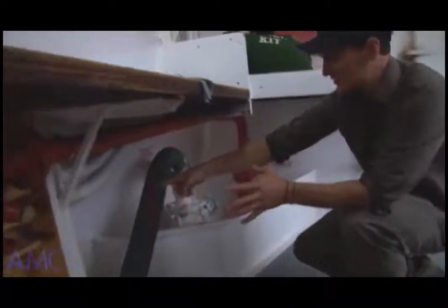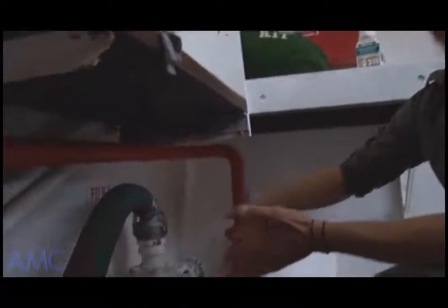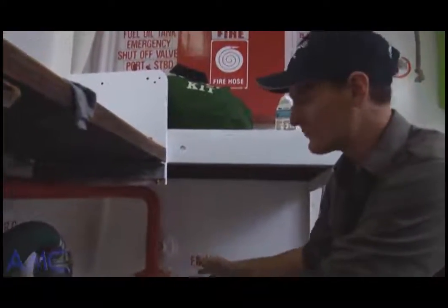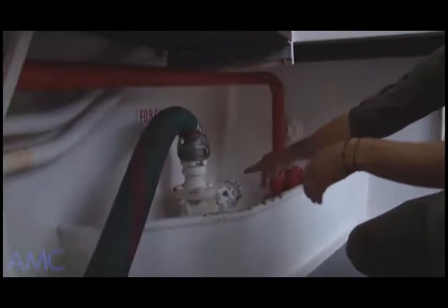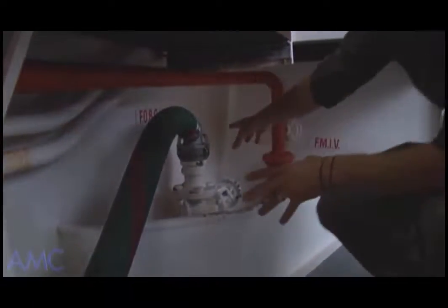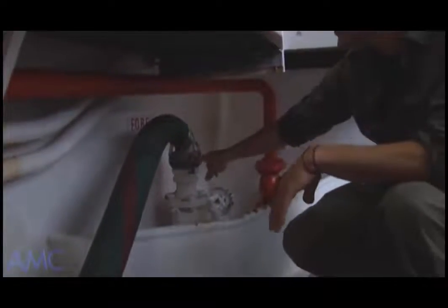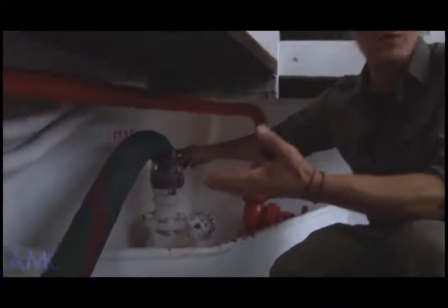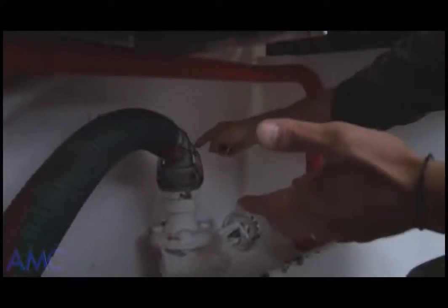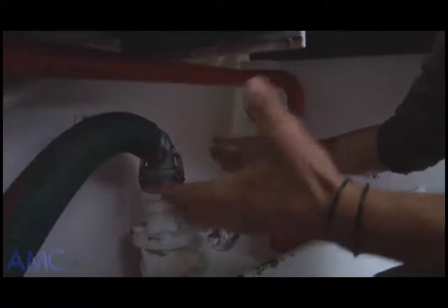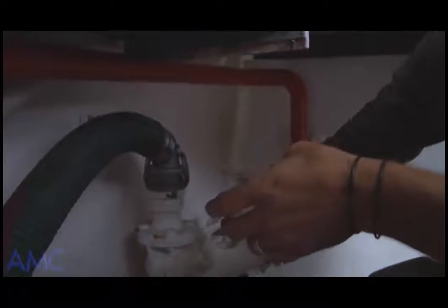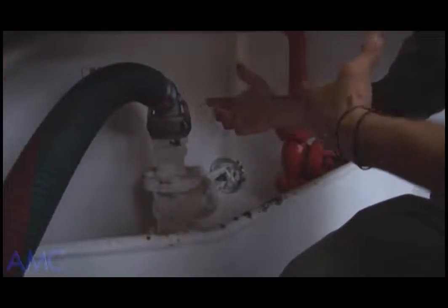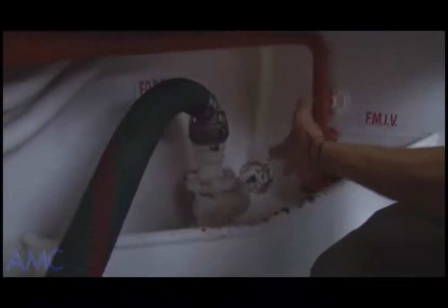So this is positioned in a bunded area or with a catchment, a save all, and this goes onto our refueling point. This one uses Camlock couplings, and it's been locked with mousing wire so that they can't inadvertently open through vibration or any other means. And we have our refueling valve, and then we can put it into either of the bunker tanks depending on which valves we open downstairs.